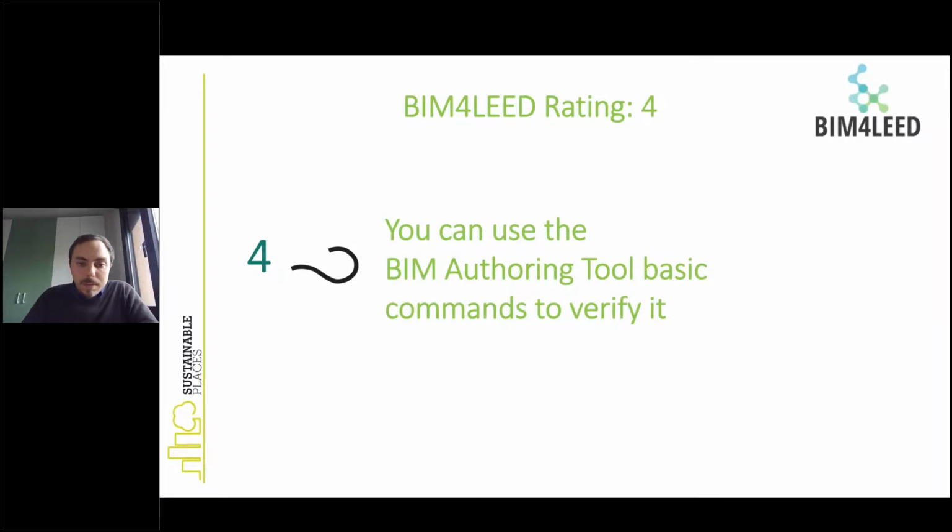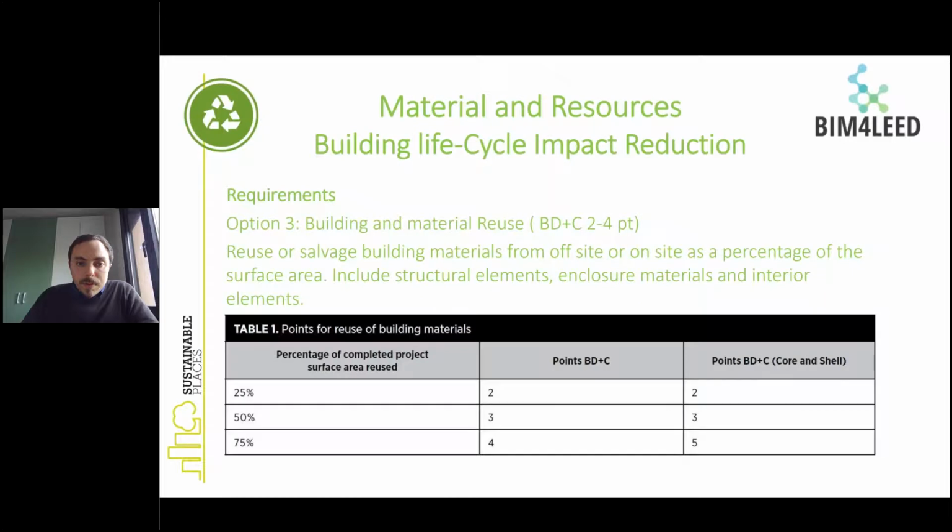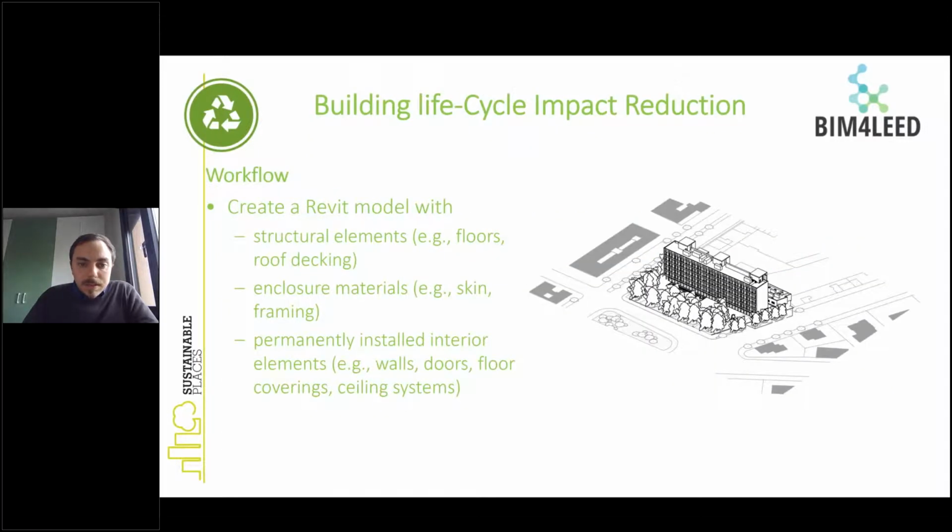when you can use the BIM authoring tool's basic commands to verify a LEED credit. So, for example, there is also the building life cycle impact reduction, but not for a new building, but for a renovation building. And for LEED, there is an option, option 3, that has different rules to calculate this building life cycle impact reduction. That is to calculate the percentage of reused materials. So the same case study as before, the headquarters of Prometeia.